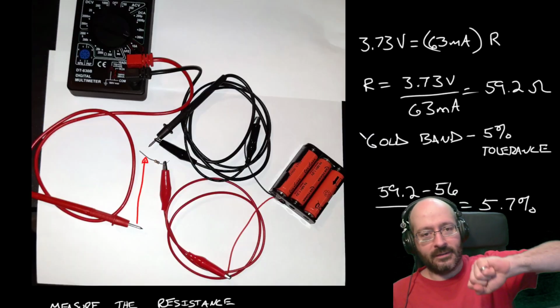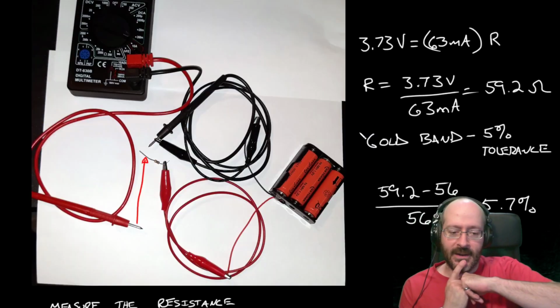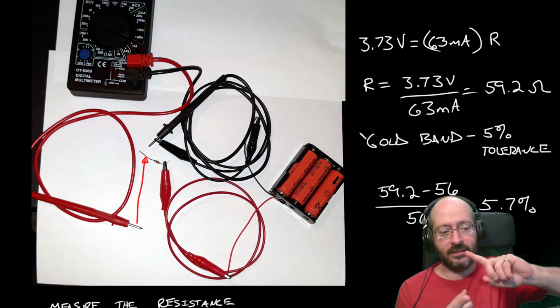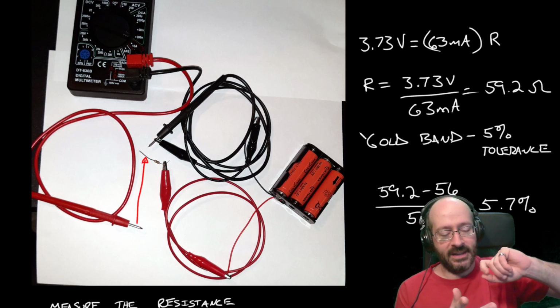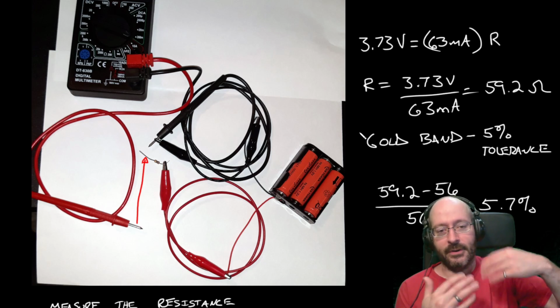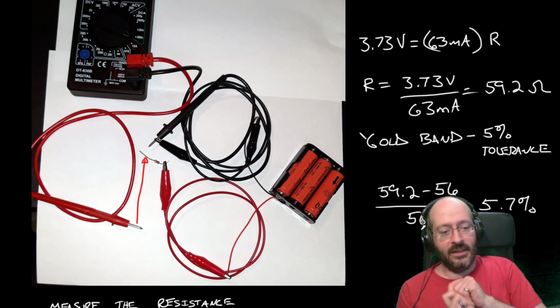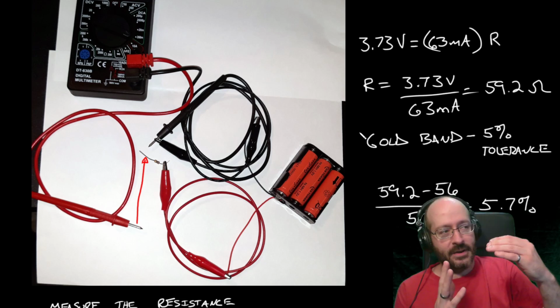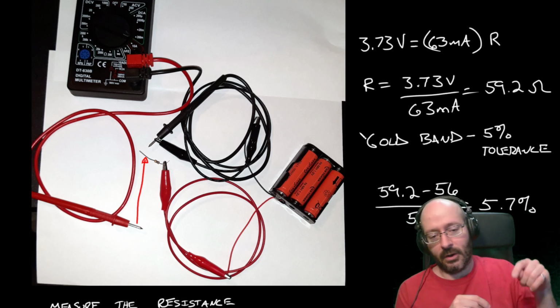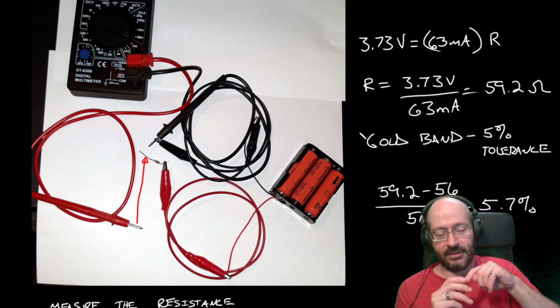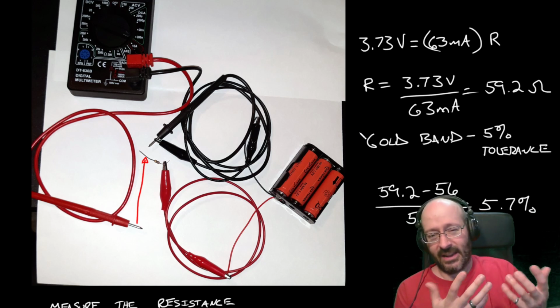So Ohm's law. Kirchhoff came in and did his work with his two other fundamental laws, his voltage law and his current law. Voltage law says if I put energy into a system and I return back to where I started, then all of the energy I put in has to drop back out. So all of the voltages around a loop in a circuit have to equal 0. All of the energy in has to come back out. It has to be conserved.